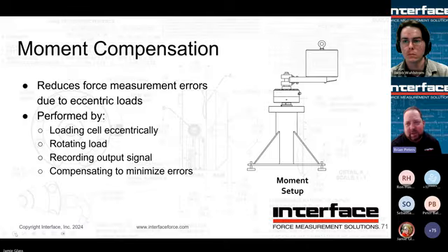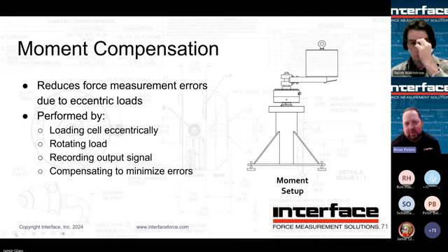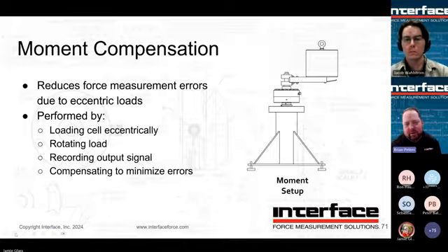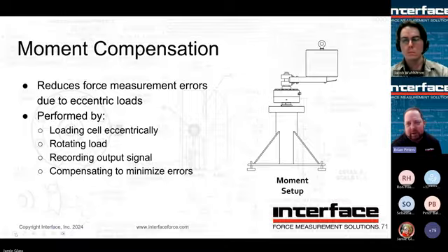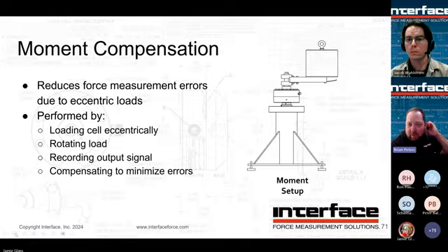So as depicted here, there's an LP bolted down to a base. If it's an 1100 or a 1600, that's going to be a base it ships with, for example. Otherwise, it would be a representative base, gets bolted down. This is before we put the diaphragm covers in, so the gauge cavity is exposed. Every unit, of course, is serialized, so the operator will load up that unit. It'll say, this is an 1100 series, this is the moment spec that we need to hit. And the operator then applies a pretty substantial load to it, much worse than would typically be seen in a proper application, at least.